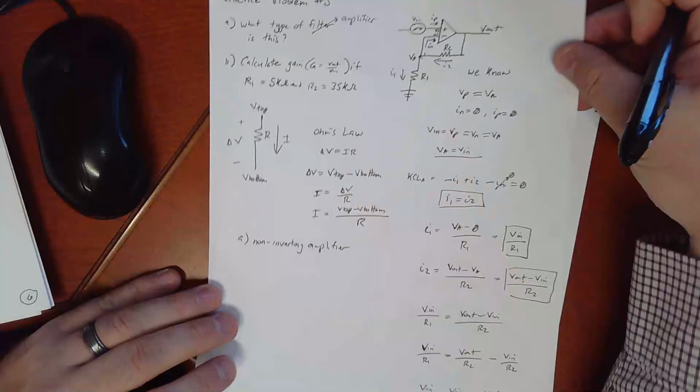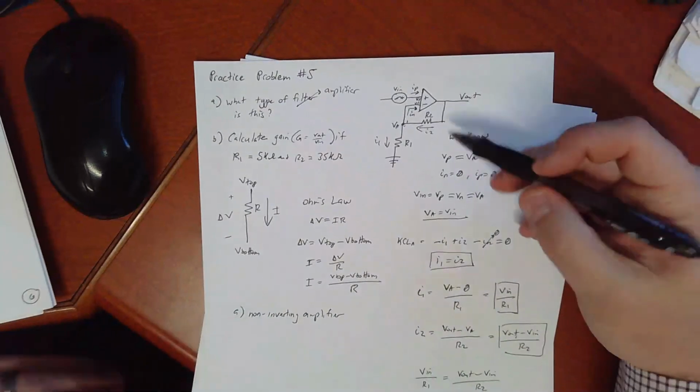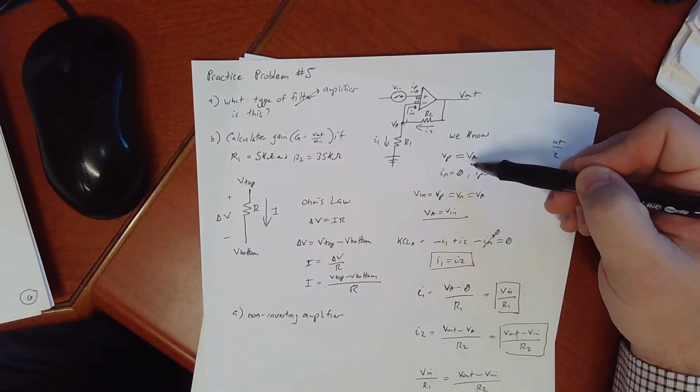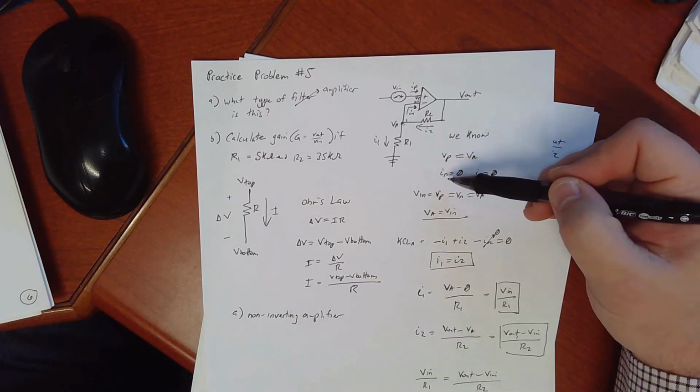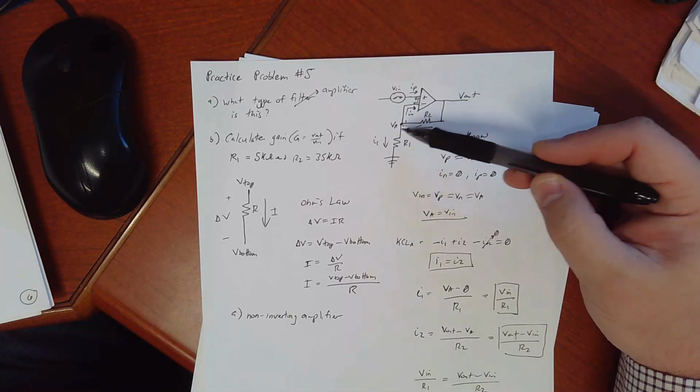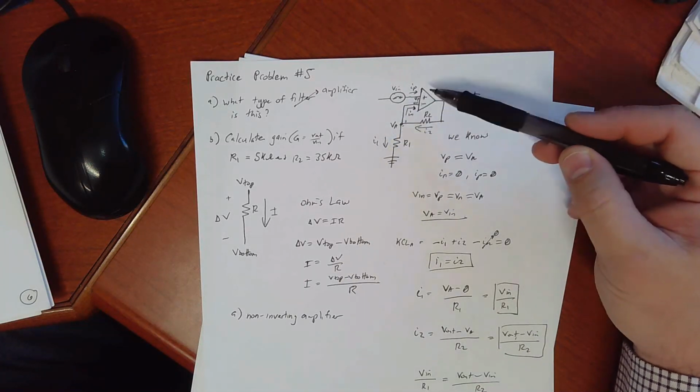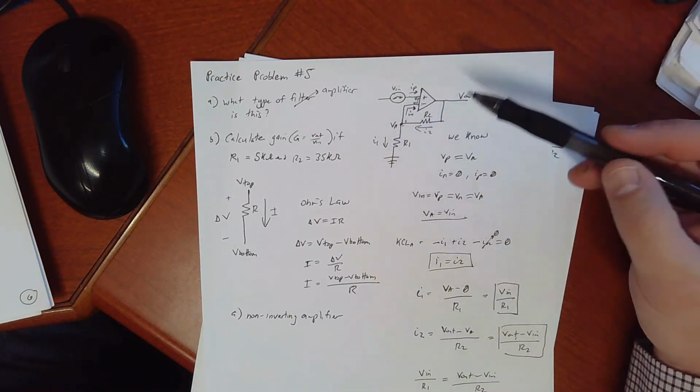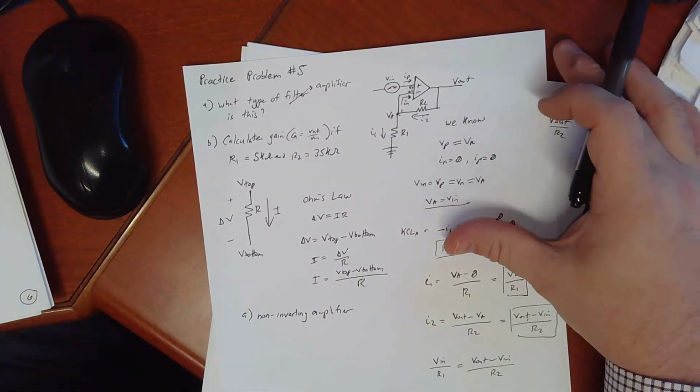You can see again with an op-amp circuit, all we're doing is applying these op-amp rules, knowing that these voltages have to be equal, knowing these currents are 0. We use that to set up a very simple KCL relationship. Then we don't even use this, right? We ignore it totally. And if so, we can solve for the equation.